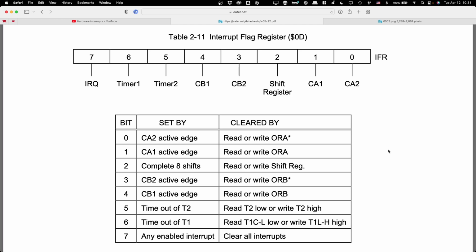And since I know which bits are in which positions, I can say, okay, the first and the third button were pressed, and then do something in my program based on that information. And when I read that register, it will clear this interrupt flag, and that basically says, all right, 6522, I see you, I've dealt with the interrupt, you can calm down now, and we can all resume normal operation until a new interrupt gets triggered, in which case we'll deal with it.